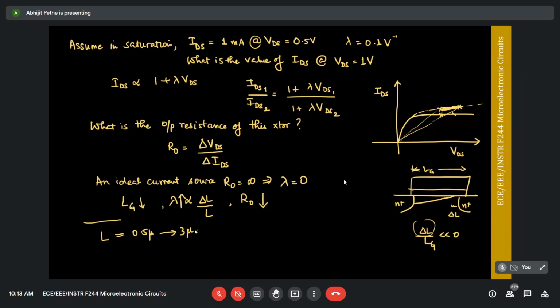What has happened of late is, as technology scaling has sped up, gate lengths have gone into the sub 20 nanometer regime, or 20, 30 nanometer regime. So in that regime, a technology person will not be able to support these multiple gate lengths for you. So then you end up having problems where you have to design an analog circuit with really poor transistors. So you'll see therefore that analog design continues to be a lot in demand, because every new technology requires a new approach to design, because it might be possible that the old design will absolutely fail in the current technology.